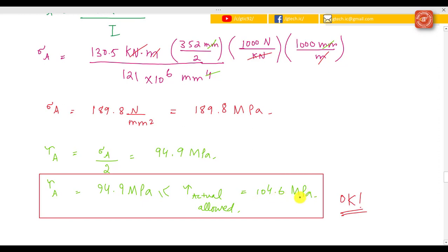So in fact our I beam is going to be able to withstand, within our design constraint, the stresses that are experienced at the outer fiber, or at point A, and so we are okay there. We will continue on by checking the junction of the flange and the web and the neutral axis, and if they all work we will be good to go.